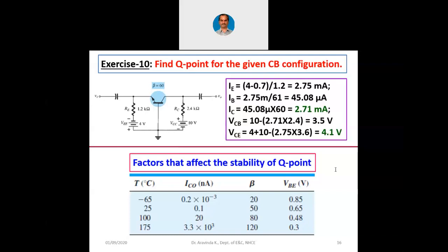There is something called thermistor, there is something called sensistor. Any material can have a positive temperature coefficient, and any material can have a negative temperature coefficient. So it does not mean that when the temperature increases, resistance also increases for all the materials. It is not so. It is selective, because we have conductors, we have semiconductors, we have insulators. We have different types of materials. All these materials will have different types of properties. So don't come to a conclusion that when temperature increases, resistance increases. It does not do that.